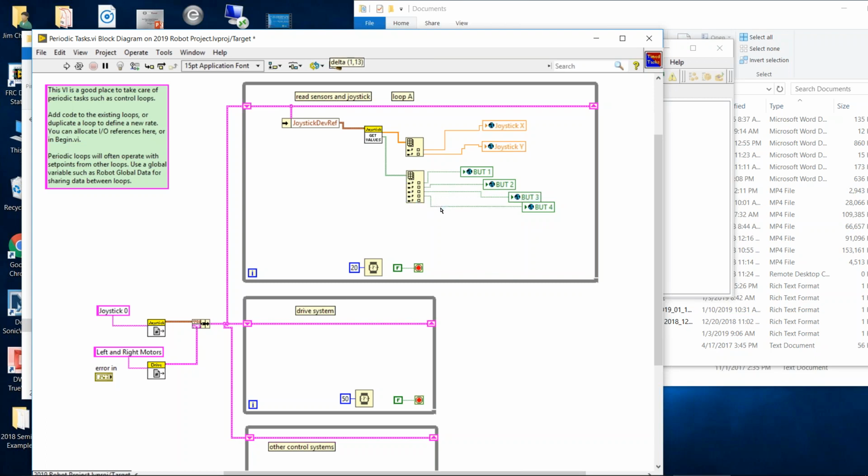Now, actually, what I want to do is move this out of the way. Now I need to hook up button 7 to the bottom, so I'm going to select, hold down control, bring down another copy of this, make this button 7. Now button 7 is in here, but it's not in the series that I've already established. So this started with 0. Element 0 is button 1, element 1 is button 2, element 2 is button 3, and the like. So if I want to get to button 7, I need to create a constant and make this 6. At that point, it's going to give me button 7. If that doesn't confuse things, you're a better person than I.